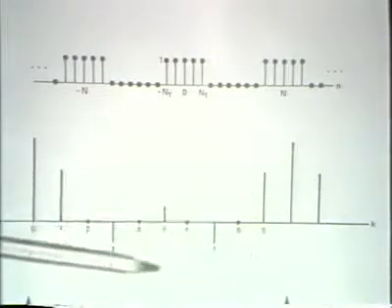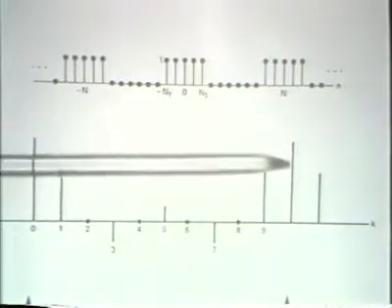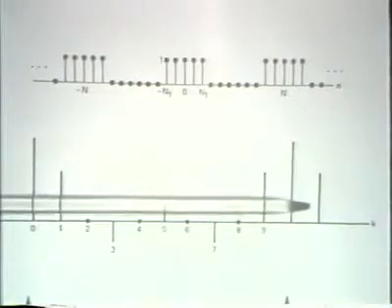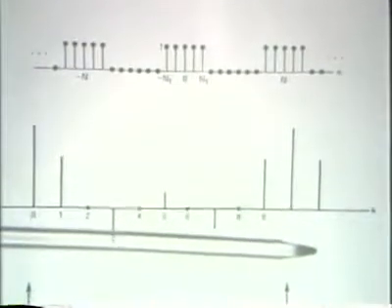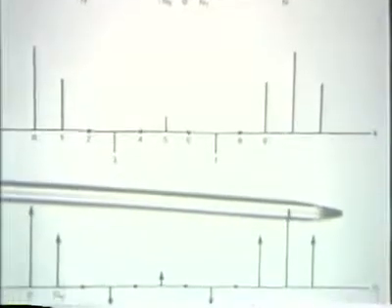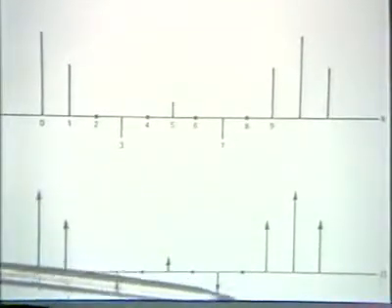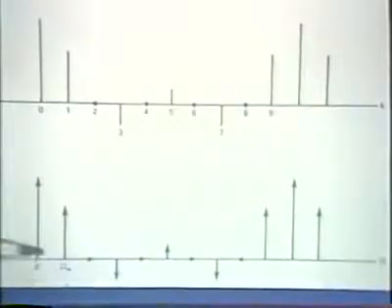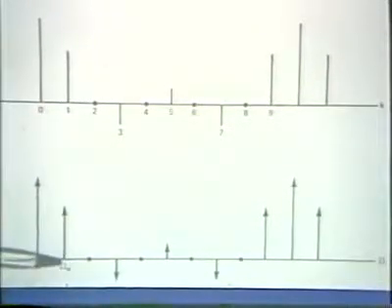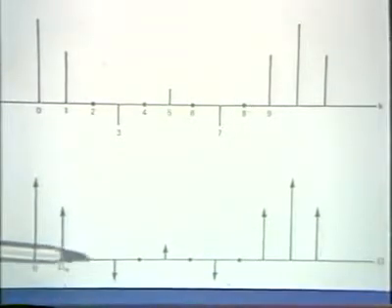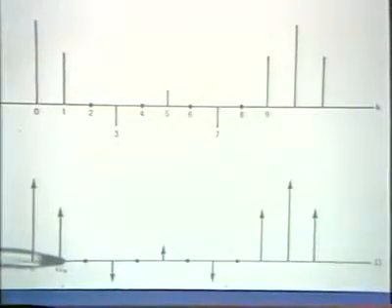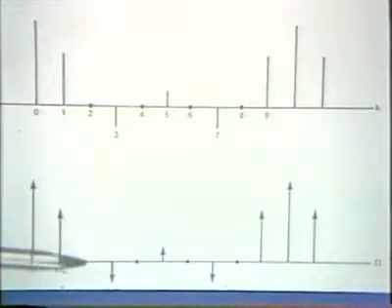So this represents a bar graph. And if instead of talking about the Fourier series coefficients, I want to talk about the Fourier transform, the Fourier transform in essence corresponds to simply redrawing that using impulses and using an axis that is indexed on the fundamental frequency omega 0 rather than on the Fourier series coefficient number k.